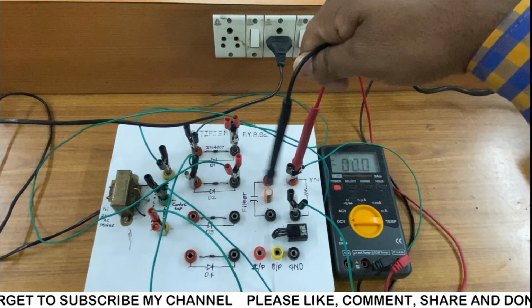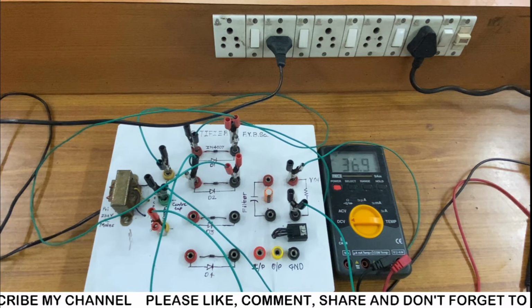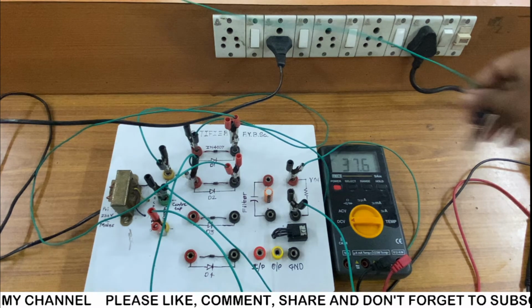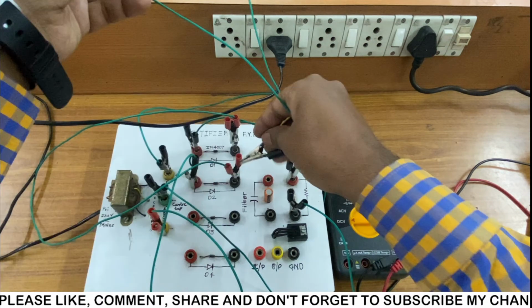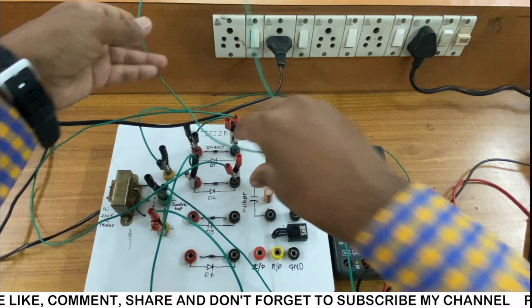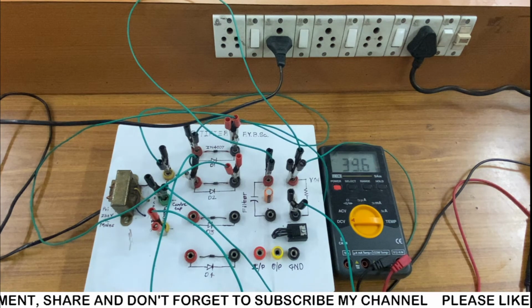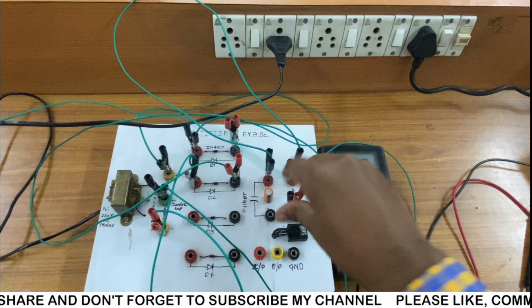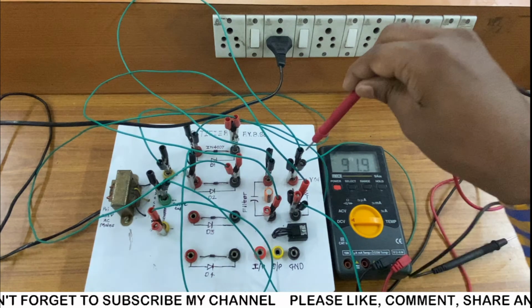With C filter, so I am going to connect again the same procedure. RL's one terminal is connected to the capacitor's positive terminal, so that it will become across the resistance RL, so it will be in parallel with resistance RL. So I'm going to connect the next resistance terminal to the capacitor. So you can see now this is the with C rectifier.